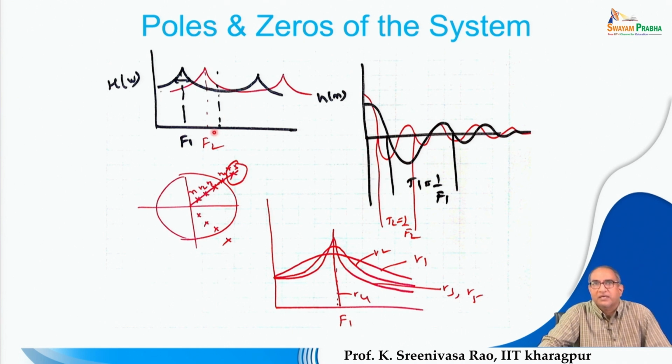These concepts are not new. You can observe similar concepts in the case of continuous time systems. If you analyze a Laplace transform, where the Z transform concept is nothing but the Laplace transform, the unit circle corresponds to the imaginary axis, and the space within the unit circle corresponds to the entire left half of the plane.